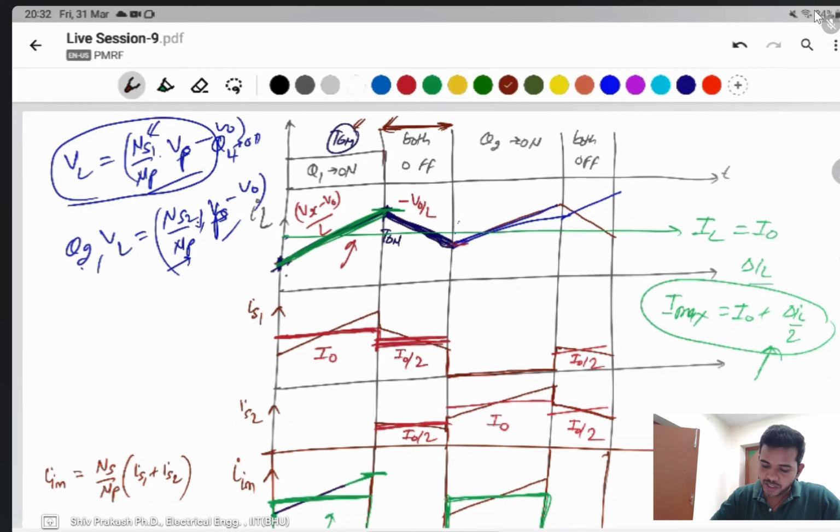If Q1 is on and after that Q2 is on, at that time you should provide dead time to fully turn off the switches. But here you have enough time to turn off the switches. The switches' charge carriers are removed at that time.